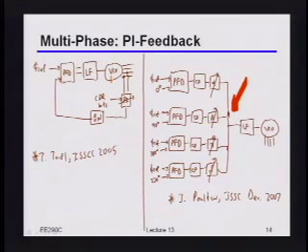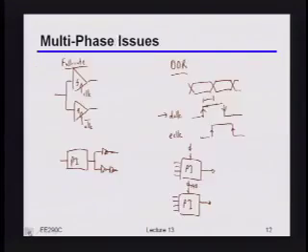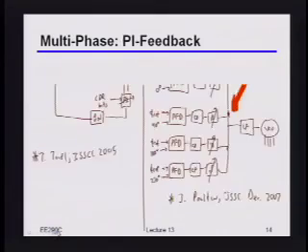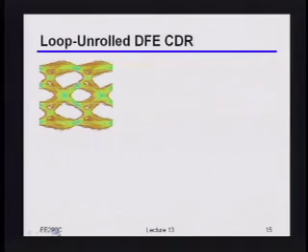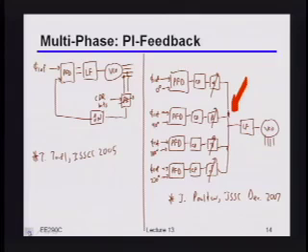What do you mean? Remember, the reason you want to do this at all is so that you get multiple phases all with the same phase shift on them. Right. But if I have a full rate system where I just need one phase interpolator anyways, it doesn't really buy me anything. Sure. Okay, great, unless there are more questions on this. Oh, yeah, so the taps are controlled.